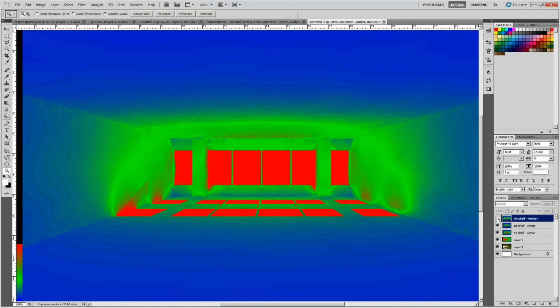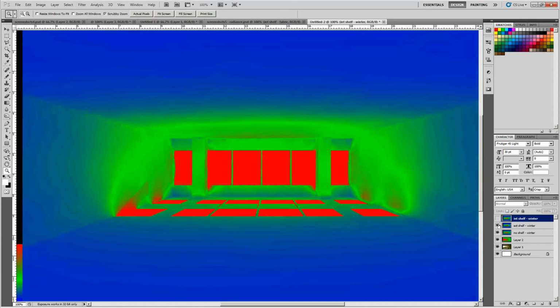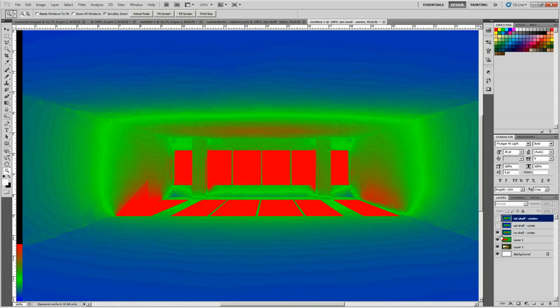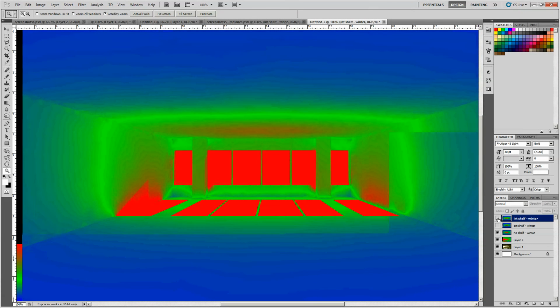And let's not forget that the benefit of the exterior light shelves is actually also that it shades a large portion, which these images are not so much about. It was the previous things, the previous diagrams we did. But so that's kind of interesting. Now we can compare no shelf and interior shelf. So there is a reduction in light, right?